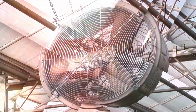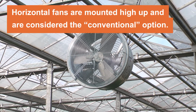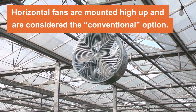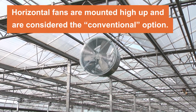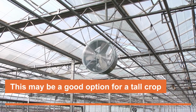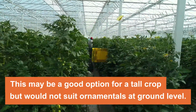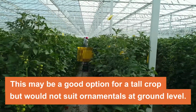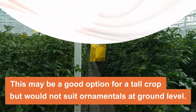A horizontal fan setup can be regarded as the conventional option for generating air movement. These fans tend to be mounted above the crop and operate by moving air in a horizontal plane to create a circulation pattern. This can be a good option for a tall crop as it will stimulate airflow through the plants, but it may not be the most effective solution for ornamentals at ground level.